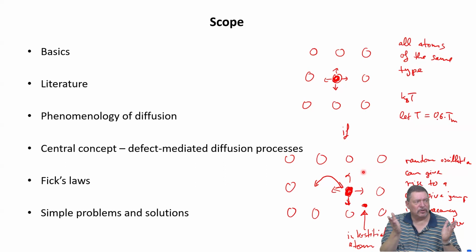This gives you a diffusion profile, and you can properly evaluate the self-diffusion coefficient, or the tracer diffusion coefficient to be correct, from these types of measurements. This is what I will show you later in this course, because this is the only way we can measure diffusion coefficients which are very easily interpretable as the self-diffusion coefficient.